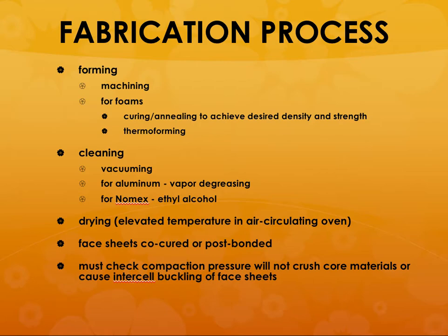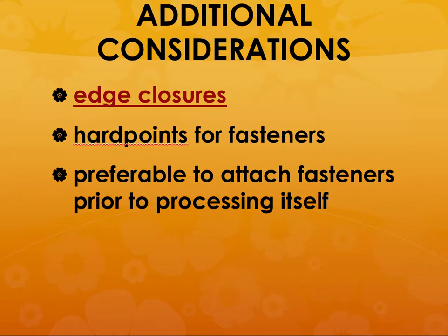One thing you have to make sure is that you are not crushing the core material, because the core materials are going to be extremely lightweight and fragile. So you want to make sure that they are bonded properly to the face sheets. And there should not be any kind of intercell buckling that takes place during the curing process.